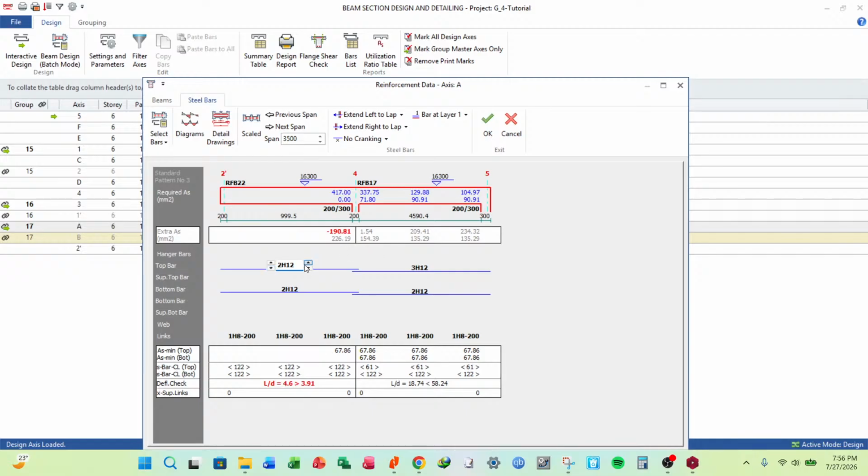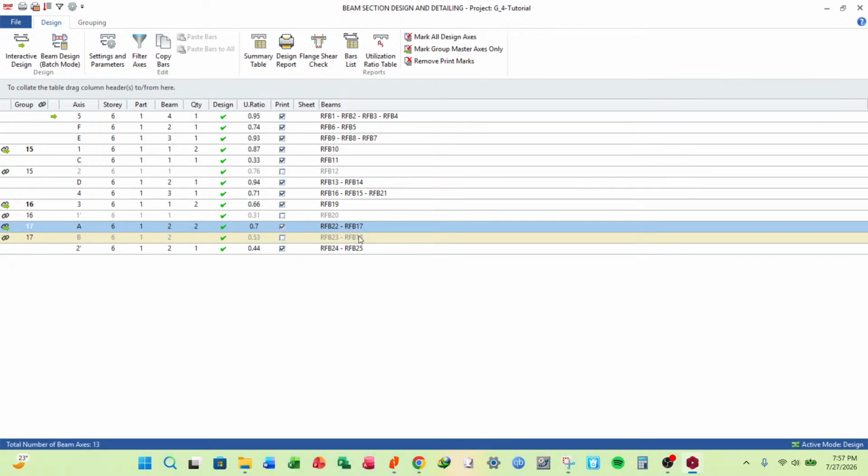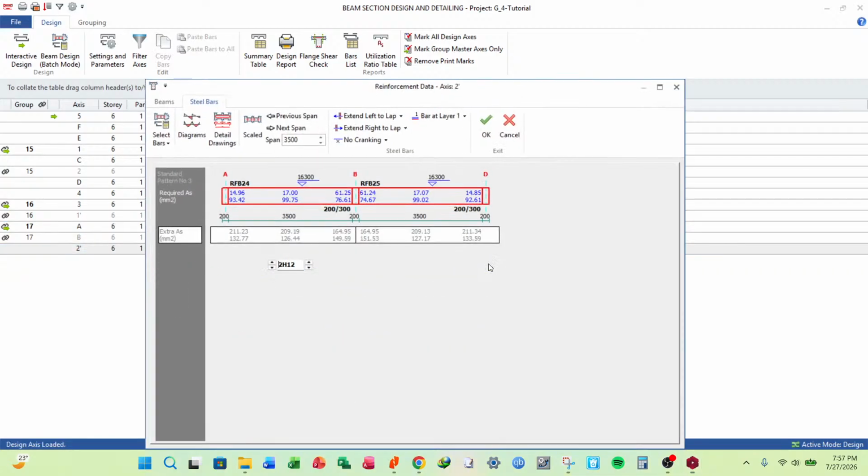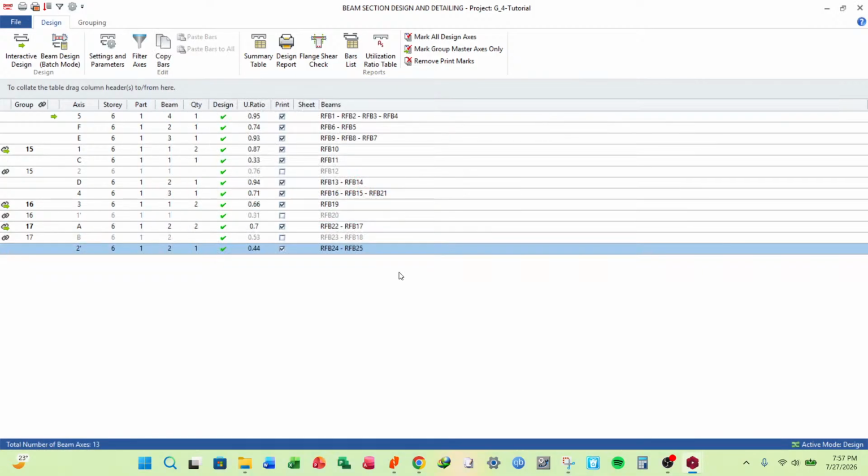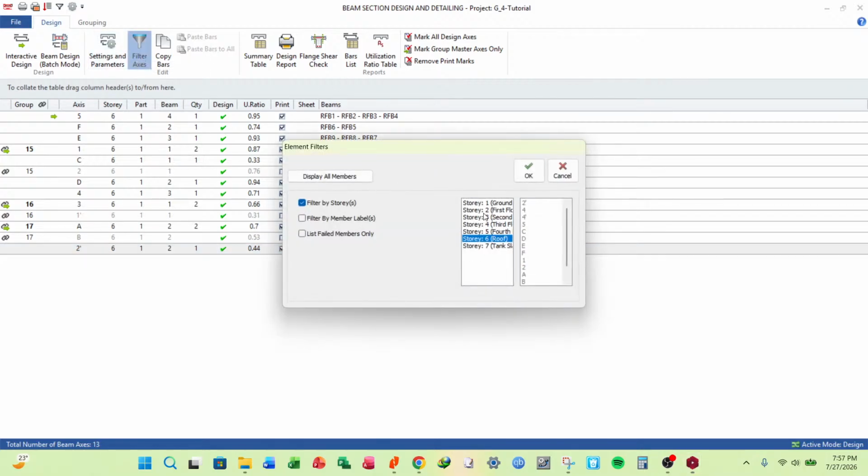Okay, since this is a cantilever, let's maintain 16 up, 2 16s up. And see it is over deflecting. Okay, actually 3 16s. 3 16s up and 2 12s down. So this is a critical roof beam. Okay, so 3 sections at the ring beam level.